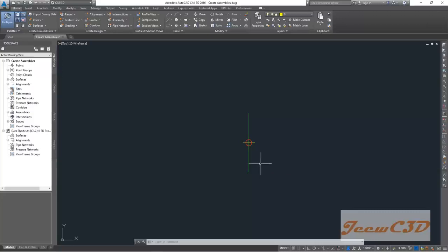So to be a cross section, you have to add parts to either side of this. You can remember we have a lane width of 3.5, 1 meter hard shoulder, 1 meter soft shoulder, and other drains and cut and fill sections.